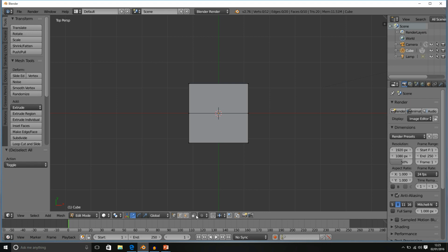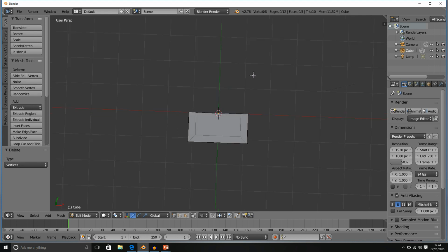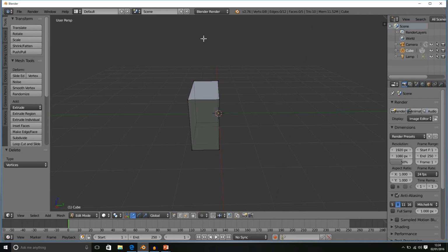We are then going to make sure that our selection is not limited to visible. So now we can see our entire mesh and all of its vertices. We're now going to press B to bring up box select. Select this half of vertices, so 1, 2, 3, 4. We're going to press X and delete vertices. So what we've done is we've deleted half of our cube.